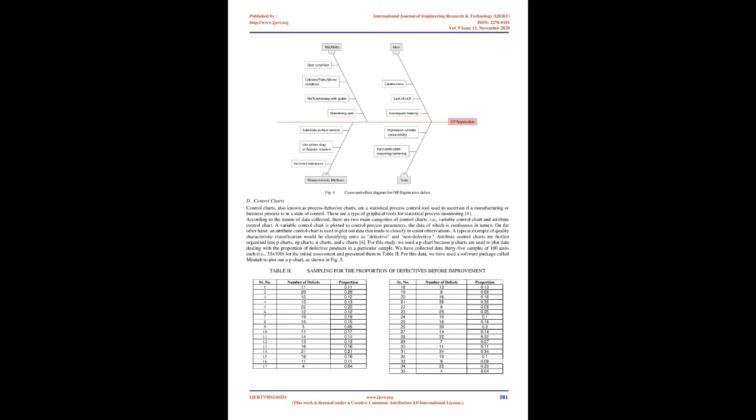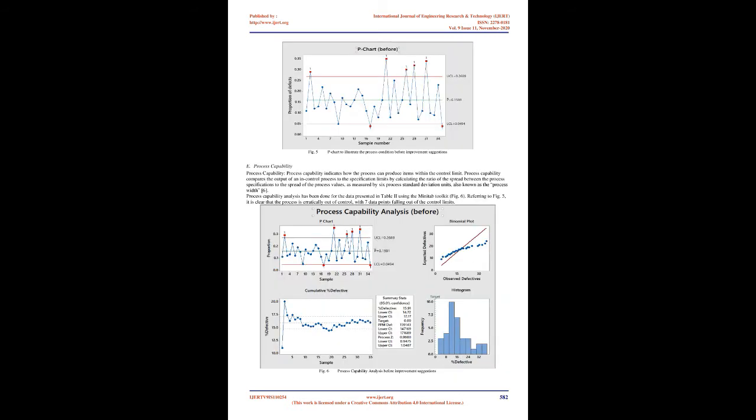C. Cause and effect diagram. A cause-effect diagram or fishbone diagram is a schematic tool used for graphically showing and analytically categorizing potential causes for a certain form of defect, signifying a cause and effect correlation between hypotheses. Although the cause and effect graphs display multiple variables that need to be studied, the focus is on the most possible cause that eventually leads to the rejection of the product. A cause and effect diagram for the three major forms of defects from Table I has been prepared for this review, namely breakage, blisters, and off-registration.